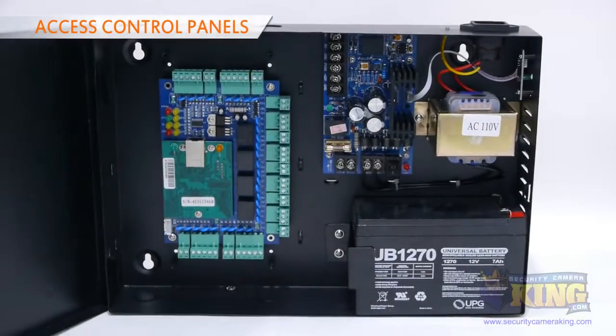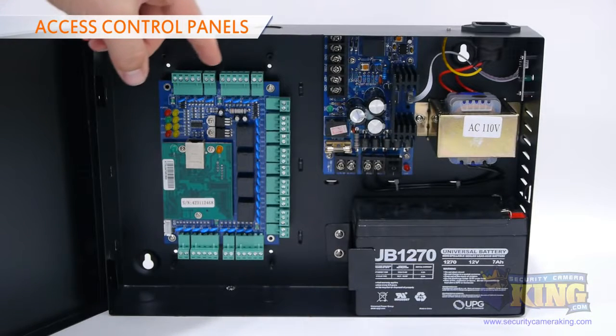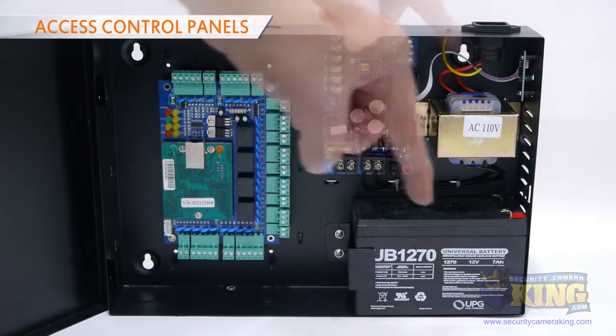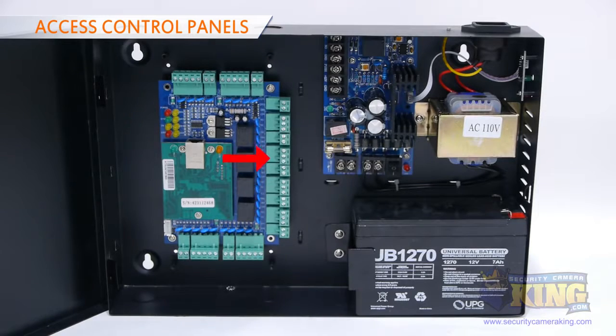Part 1, access control panels. Access control panels are essentially the brains of the system. Usually, the panel is made up of a circuit board inside an enclosed box, along with a power supply. Sometimes there is a battery backup as well. The number of access points or doors you can control depends on the capabilities of the specific access control board you use. Many come as a standard configuration, but can be upgraded as your needs change.